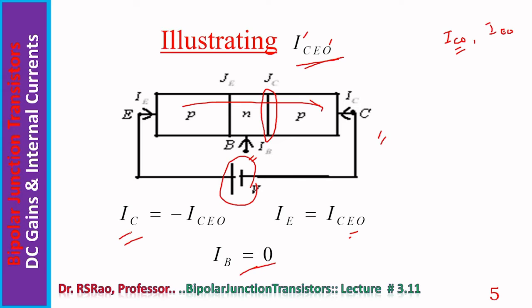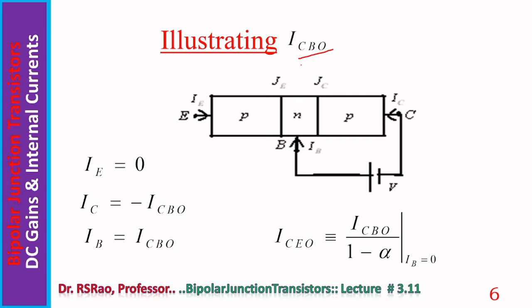IC, IE, IB are the terminal currents with directions shown in this diagram. The standard convention is that terminal currents are always entering the transistor. For them, current is positive only when current enters the transistor.